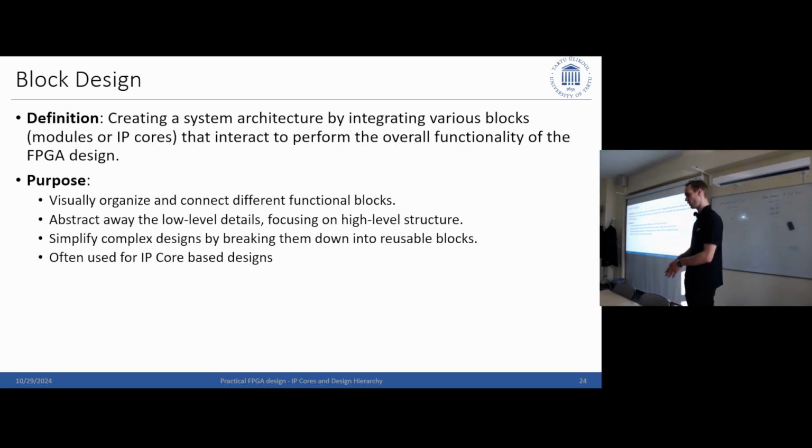The risk is that a simulation may not represent the actual behavior of something relevant, especially for a memory block, where you would have to prove that your simulation is exactly like the memory block. So the more complex the block you try to simulate, the more time you will spend on it. You might want to make a simplification, but then it does not fully resemble the block anymore. So it's a trade-off you have to make in simulations.